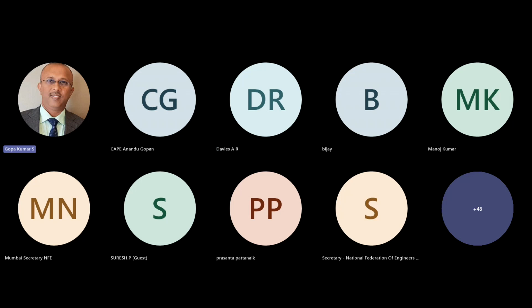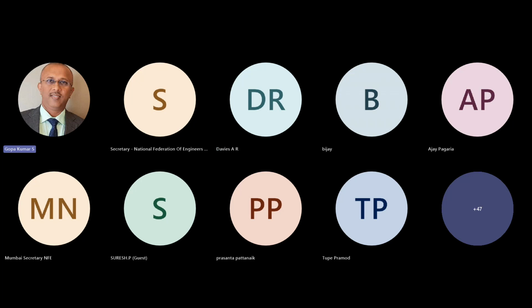Thank you, sir. If you look at the protective devices on the DC side of the solar PV, those devices are just like isolators. They will not disconnect in case of a short circuit or a fault, because the amount of short circuit current itself is quite low. That is the reason different methods of identifying faults and disconnecting the system have been implemented. A conventional system will not work on the DC side, especially solar PV. Number two, in case of any arcing on the DC side, you cannot stop it. It keeps on arcing, and it will burn the whole system.